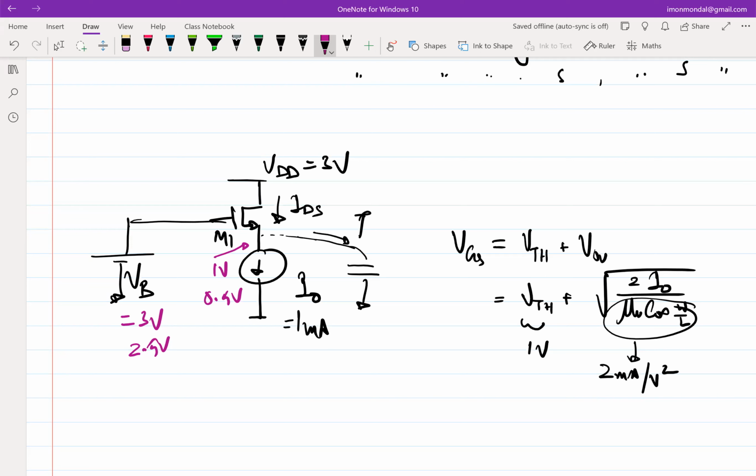Right? So the source voltage cannot be negative, this voltage at least has to be greater than 0, which means VB has to be 2 volt plus the source, so it has to be at least equal to 2 volt, right? In principle, these current sources are also made using transistors, which means that you would like to keep some drop across the transistor, across the current source, right? It will not be 0, it will be some positive drop. So in that case, you have to ensure that drop is fine, and on top of that, you have to apply the VGS. Okay, makes sense?